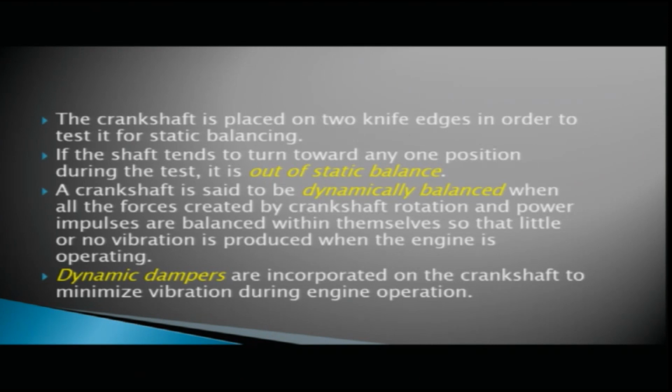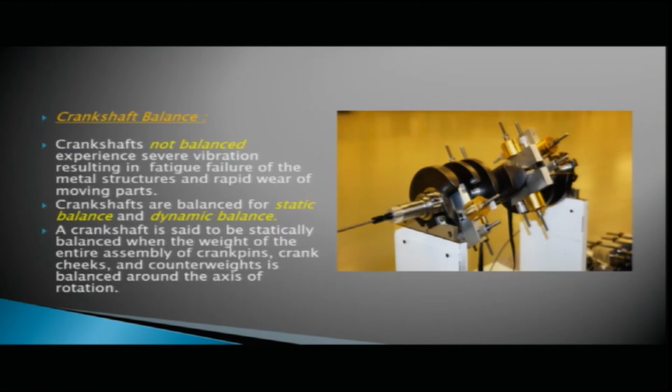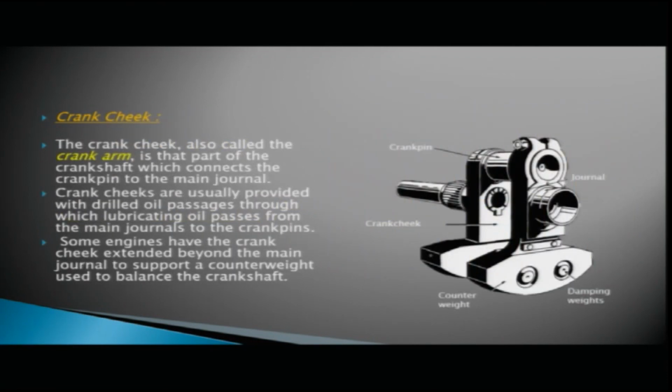Dynamic dampers are incorporated on the crankshaft to minimize vibration during engine operation. Here in this diagram, you can see the crank cheek extended beyond the main journal to accommodate the dynamic dampers.